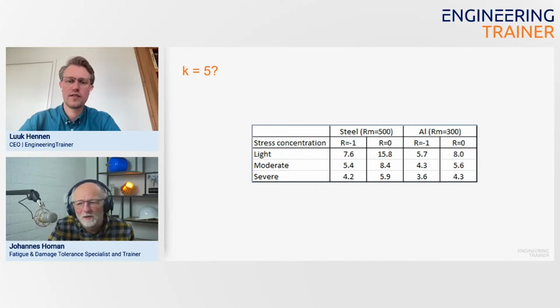The point of it is that you should recognize that those exponents can vary quite a lot depending on the severity of your stress concentration, on your loading conditions, and on your material. Yeah. And that's a bit overlooked in most of the guidelines and calculation codes.